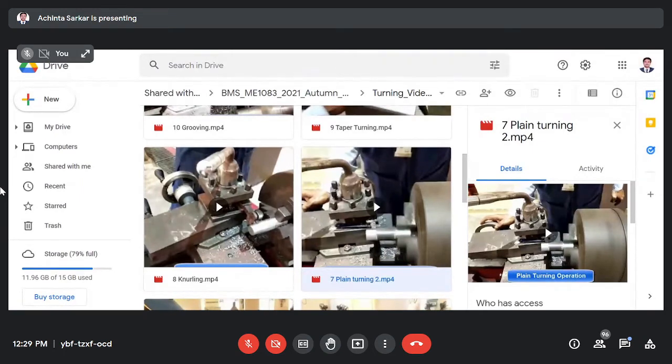Okay. So now feed is another parameter that sir explained here. Feed is when your cutting workpiece takes one complete revolution, because the workpiece is rotating there, and because there is relative motion, the cutting tool has to move. So when it takes one complete revolution, meantime the cutting tool might have moved some distance there. Suppose that distance is x millimeter. So now this x millimeter is your feed.